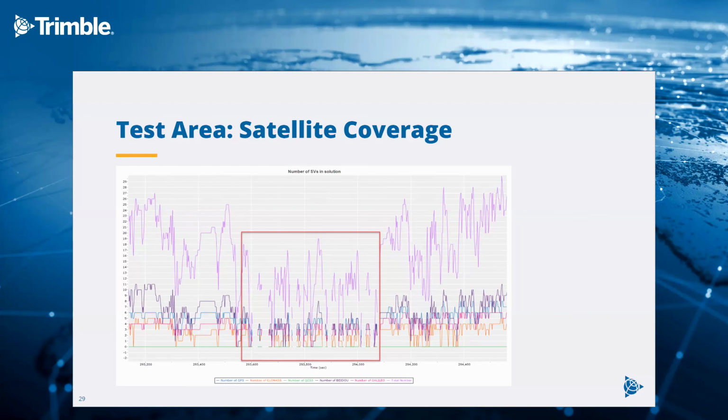So within this challenging town center, characterized by the narrow roads, as I said before, and surrounded by buildings, the majority of the GNSS epochs were in so-called float mode due to the satellite shading, and not in the fixed mode. And the highest, or let's say the worst, estimated 3D root mean square (RMS) value in the GNSS-INS Kalman filter process was approximately even 50 centimeters, so half a meter, and not better. Okay.